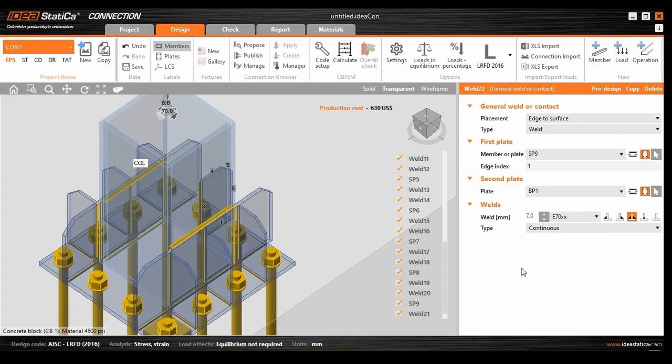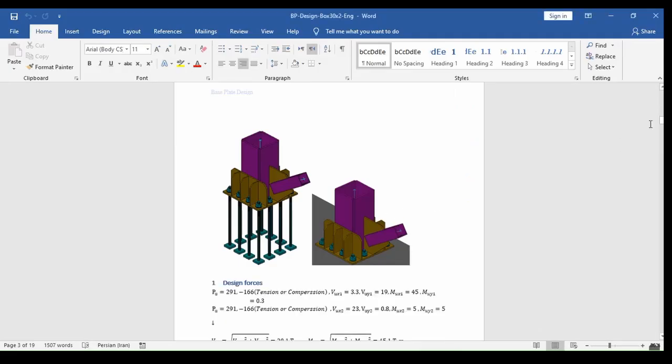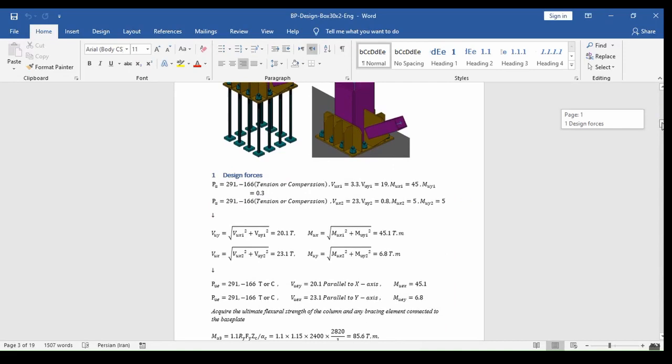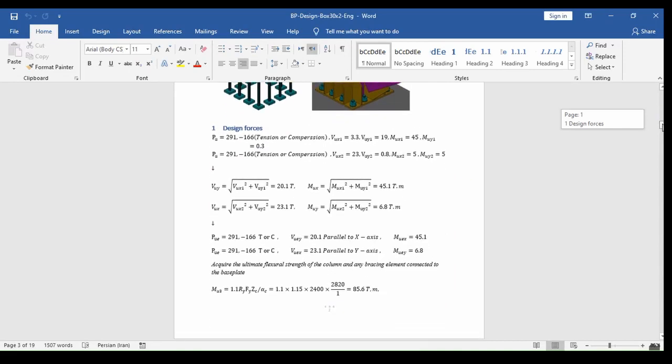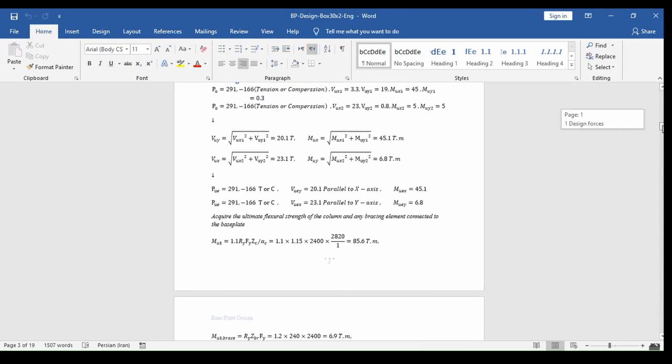The only thing that remains is the gasket plate and bracing element. For the record, you can model bracing element to connection and assign its forces based on AISC, specifically to the brace, and you can also ignore diagonal brace and add its forces to the node. For example, this is exactly what I've done here to determine the design forces for simple method design.